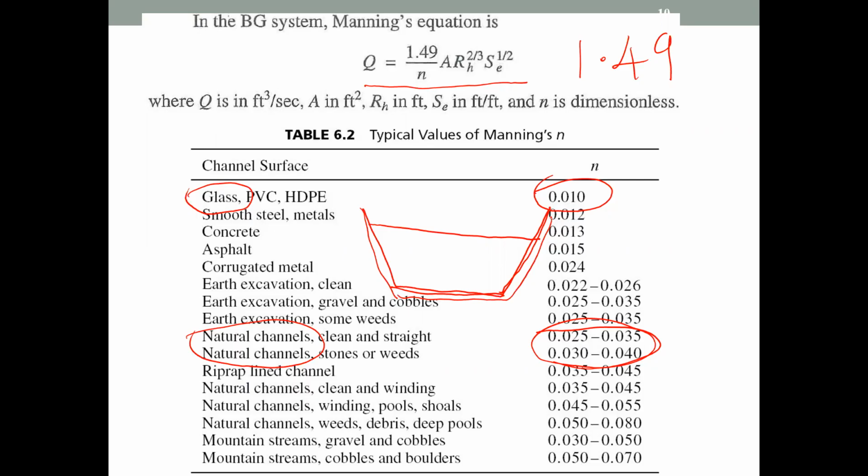So now for a given flow rate Q, there are several parameters that we need to find out. What are they? We need the area and the velocity. Velocity, the average velocity, is in terms of hydraulic radius and the slope of the EGL. Now you see we have the area here. So again, the area comes into the hydraulic radius. So this is not going to be a linear equation. This is a non-linear equation.